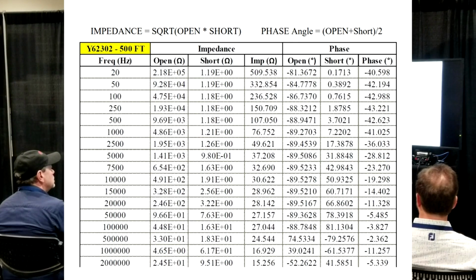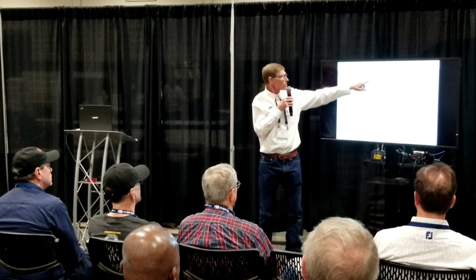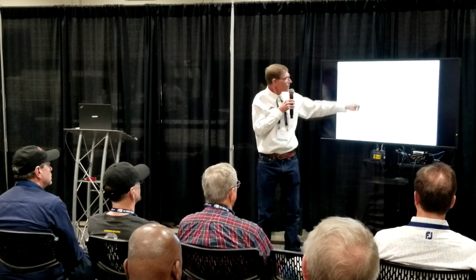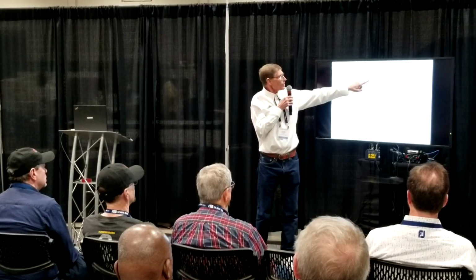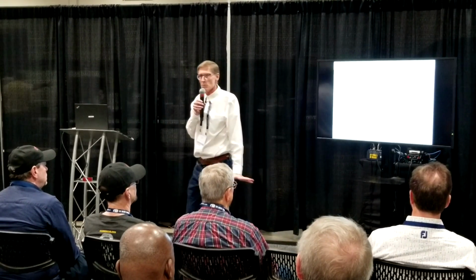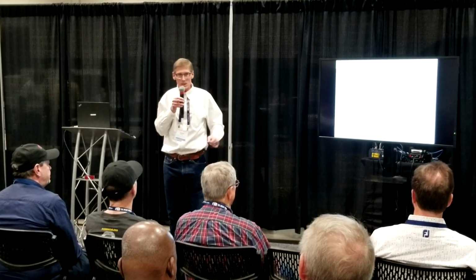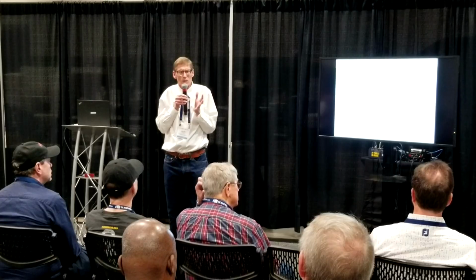When we short the ends of the cable, we have a very low resistance instead of a high. This is high to low. This one's low to high. It's kind of the opposite. So as I increase the frequency, the resistance keeps going up, up, and up, and up, and up. And that's because of the skin effect, proximity effect. All that stuff gets captured in that measurement. It can't escape. You can't really cheat.